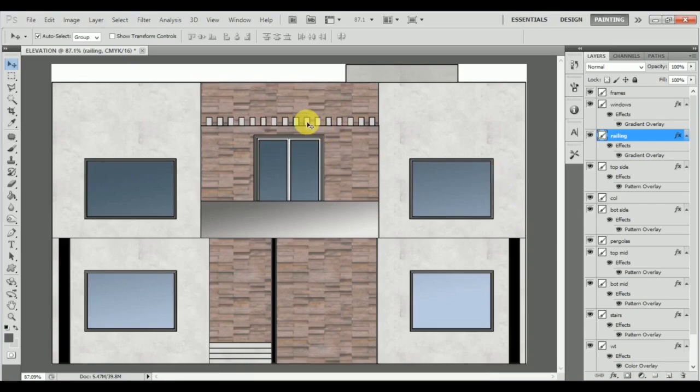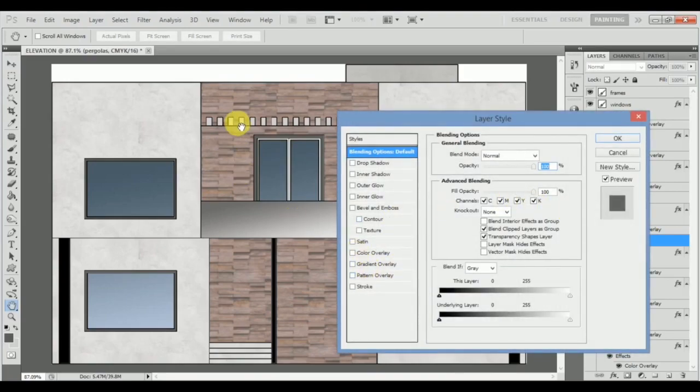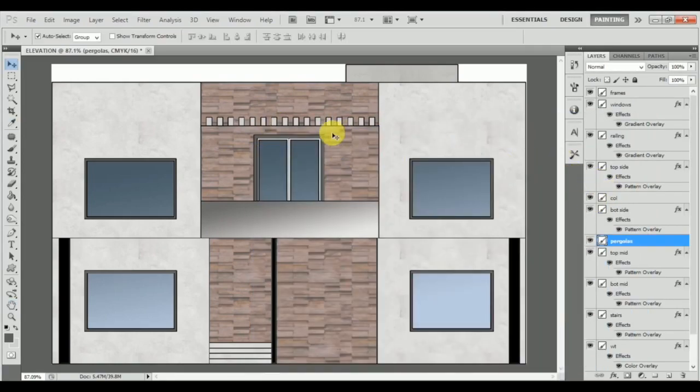Now, when we talk about the pergolas, guys, we can give it wooden pergolas, but I would prefer not, because the backing is also brownish. So I can let it be white. We can even let these pergolas be white. So what I can do is select all these layers. How do I do that? Basically all these boxes. You can see we are on the pergola layers, right? I can just press Control and click on this box. So the entire layer will get selected and all the boxes on the layer automatically get selected.